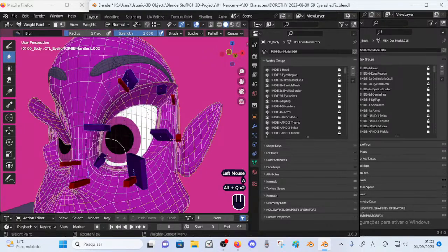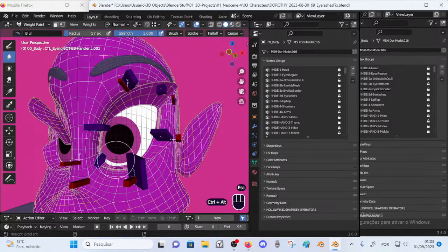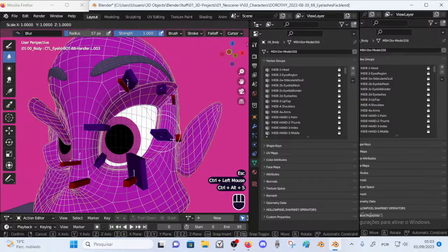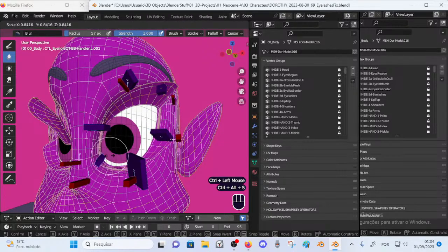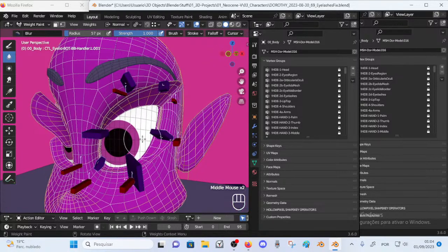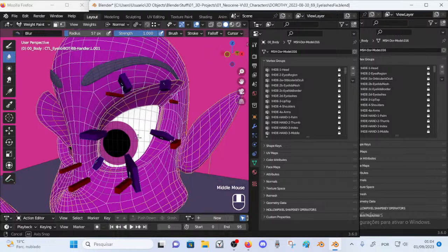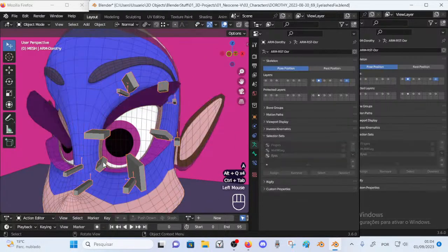I think I've picked the wrong bone for scaling. This one should be... Why changing this b-bone scale here would change the slide. Oh, I cannot. This is not pose mode or edit mode. This is why. This would be like scaling the bones.